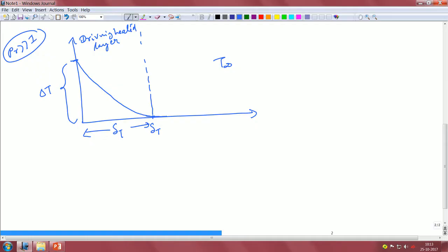So, therefore, the driver for this particular problem is essentially this heated layer. Whatever gas you are talking about, whatever is getting heated in this region around the wall is basically the driving mechanism for this buoyancy. And here you have a balance between friction, because it is a Prandtl number much greater than 1 problem, balancing the buoyancy, correct. That is the nature.